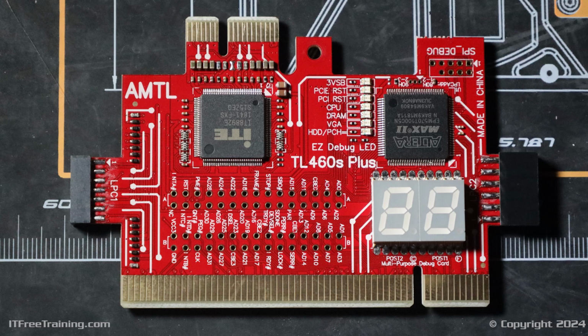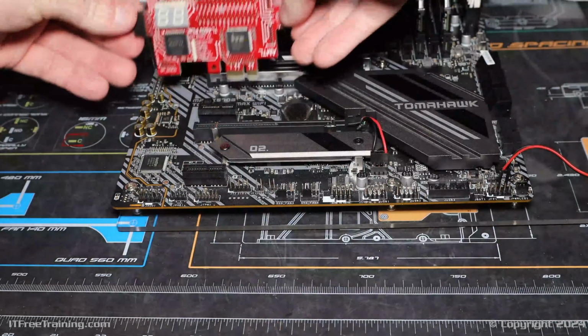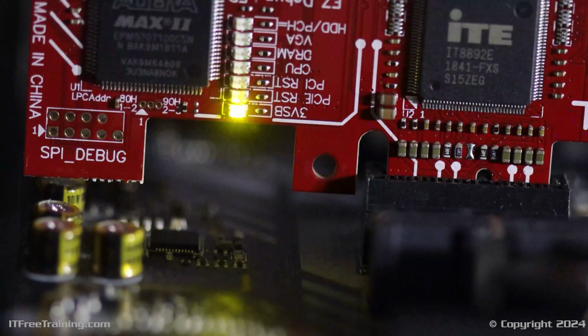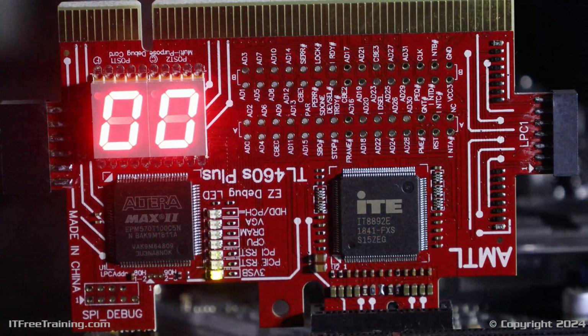To demonstrate a point, I will plug the card into the PCI Express slot. You will notice the light on the card will come on. Just another reminder, modern computers always have power running through them, even when they are off. Before installing cards like this, make sure the power is physically switched off. I will now press the power button, and you will notice that the card gets stuck on 00.